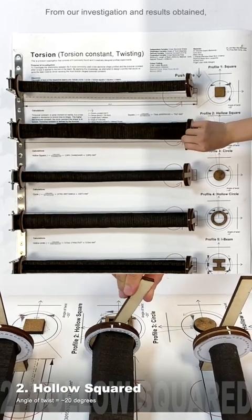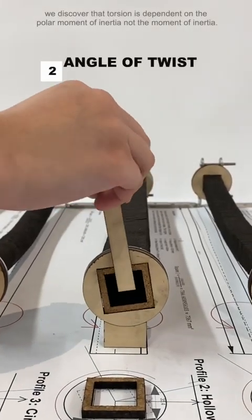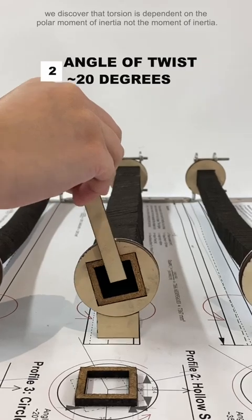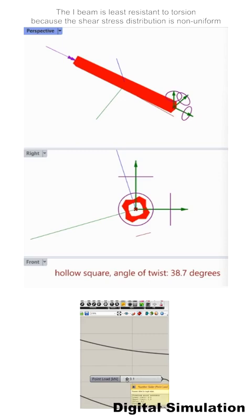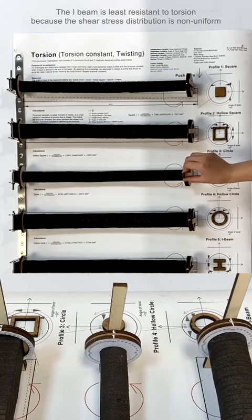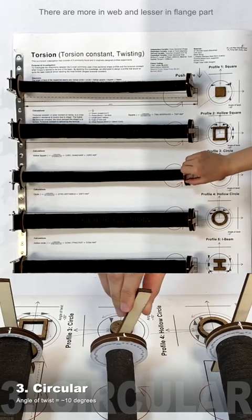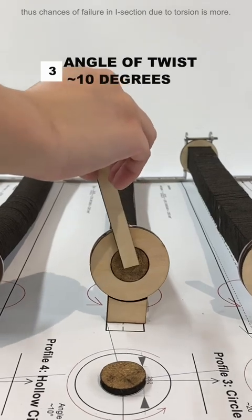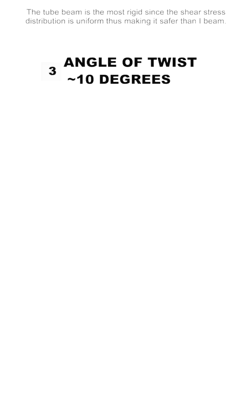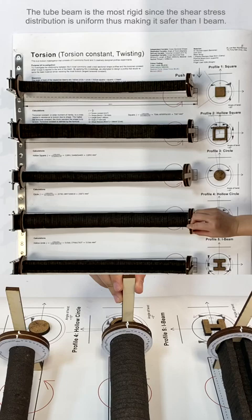From our investigation and results obtained, we discovered that torsion is dependent on the polar moment of inertia, but not the moment of inertia. The I-beam is least resistant to torsion because the shear stress distribution is non-uniform. There is more in the web and less in the flange part. Thus, the chance of failure of the I section due to torsion is higher, and meanwhile, the tube beam is the most rigid. This is because the shear stress distribution is uniform, thus making it safer than the I-beam.